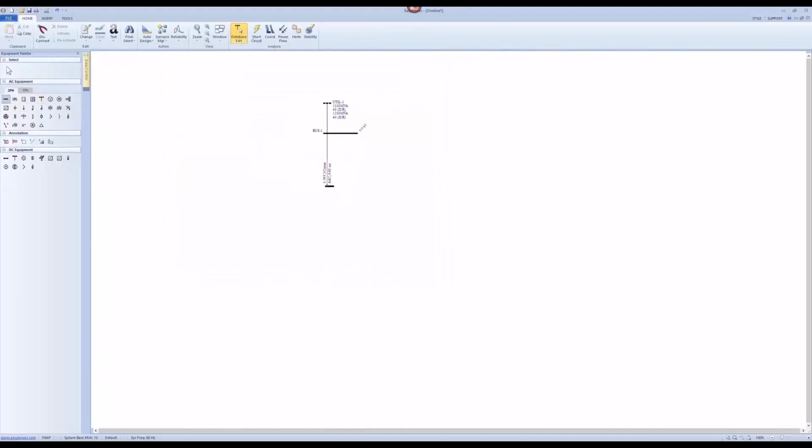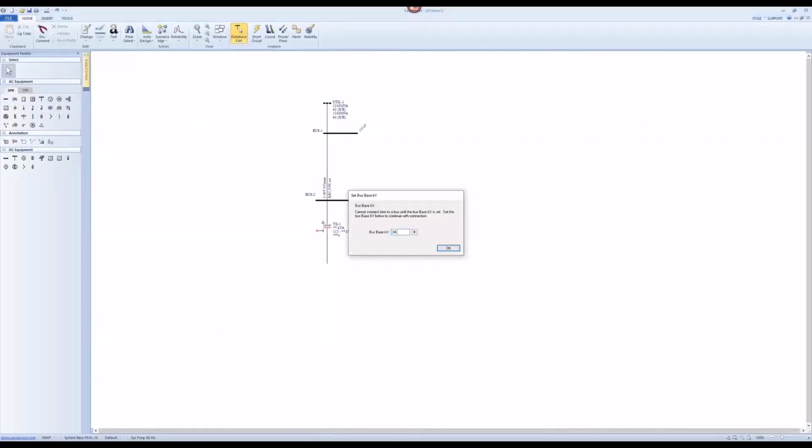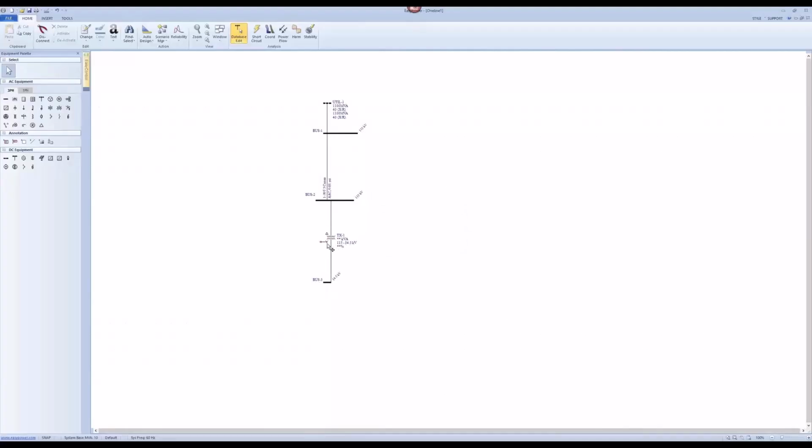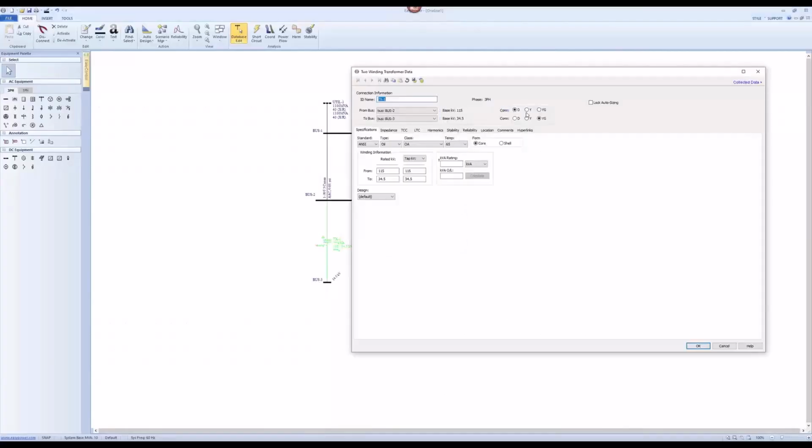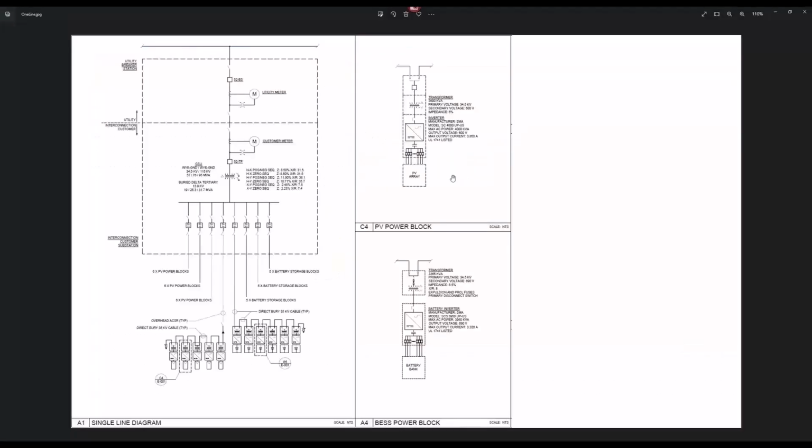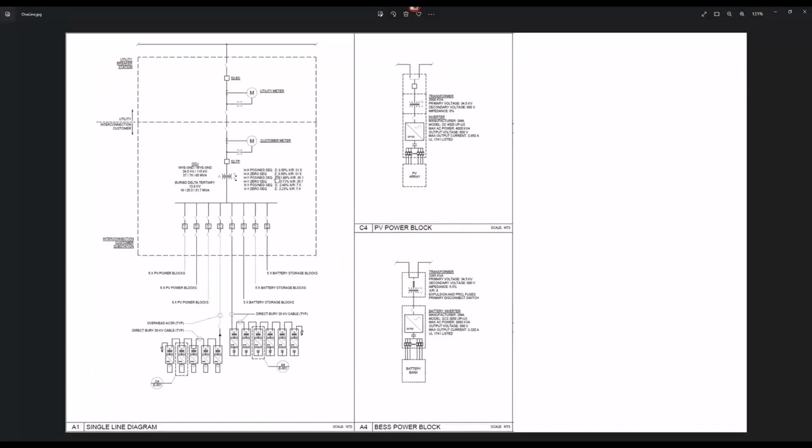And I will put the high side of the main power transformer bus, drag it longer. Now I put the transformer over there. So for the transformer, I know that my high side is 115, low side is 34.5 kV, right? Drag it longer. And usually the connectivity is YG, delta for the transformer, right? So I will enter the transformer parameters. What do I have here?